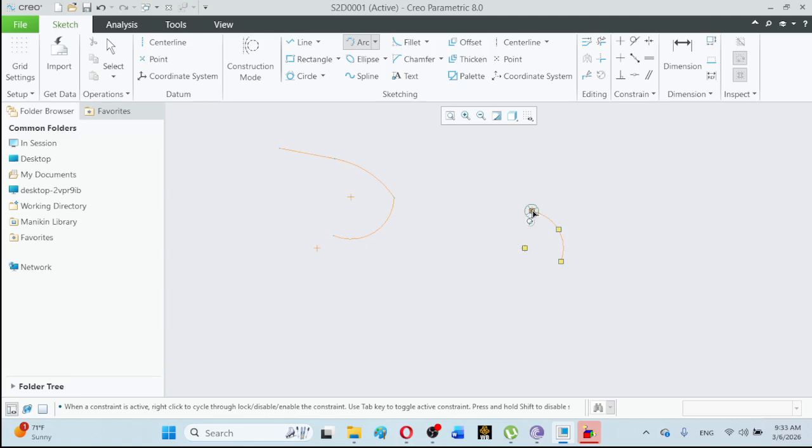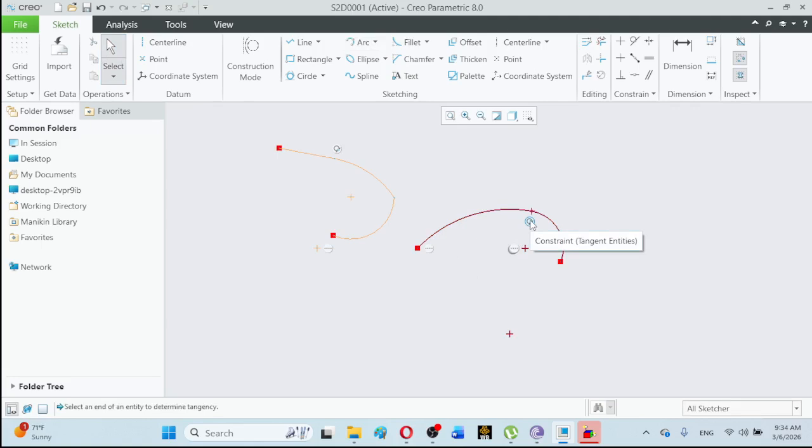But if I am moving the cursor out from this quadrant or from this quadrant, which are on either side of the front and back end of this arc, so the 3 point arc will be drawn here from this quadrant. So this is the tangent end arc here, and this is the tangent constraint, which can be reassigned and removed like this.